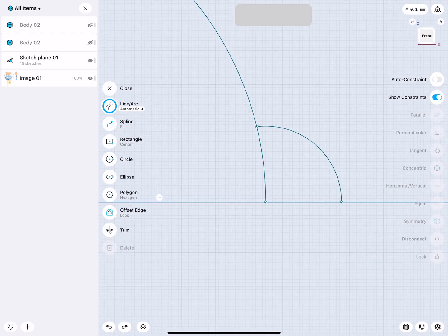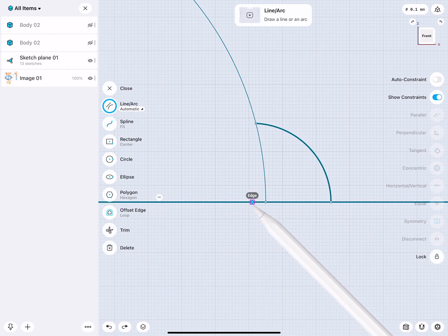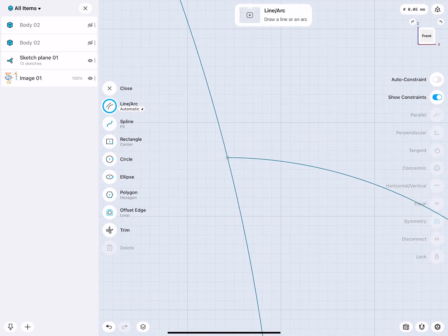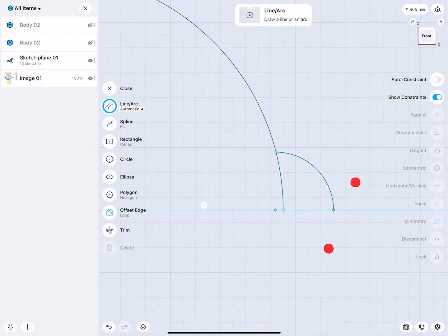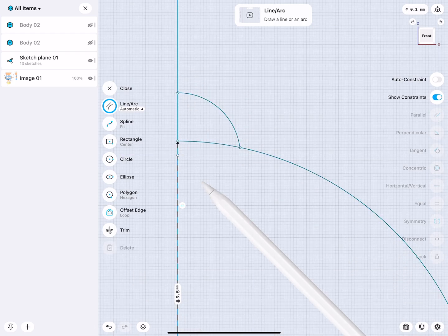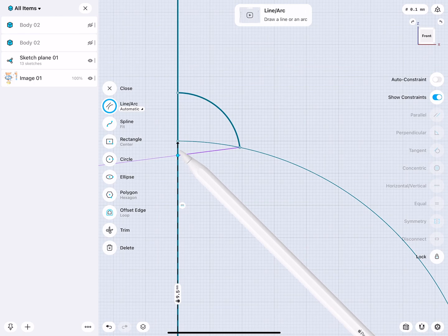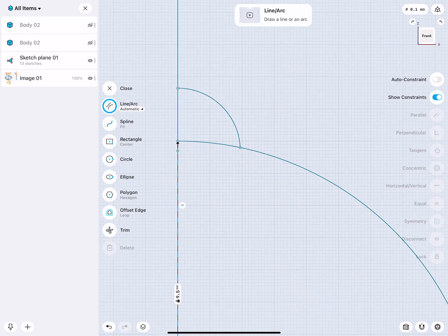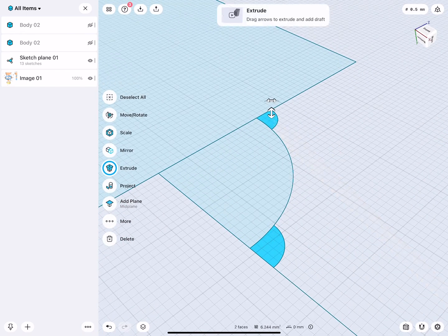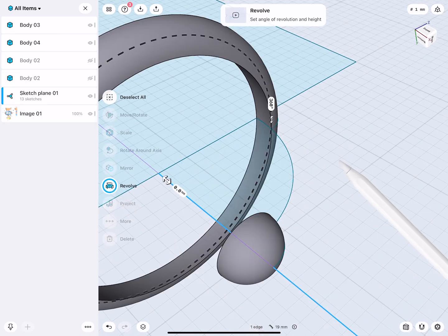I think, yeah, this is becoming, as you can see, concave, this is not good. So at this point, we want a little bit here. So right there, you see, we're not creating a cave-like object. This is important for injection molding. And maybe here, actually, we do the same. So at this point, we simply move to there. Okay, good, nice. Now these shapes I can select. Also revolve. There we are.